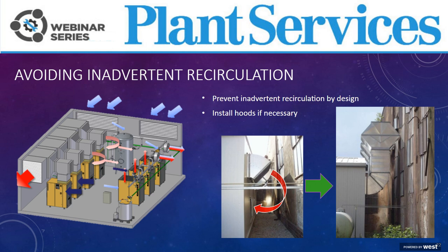Try to route exhaust air through the roof when possible, and take prevailing winds and other site conditions into account. It's typically not a problem to exhaust through one wall either, as long as the cooling air inlet isn't being pulled into the room on that same wall. If you have to do that, like we saw in the previous slide, then orient the exhaust so it's pointing away from the inlet. What we see on the far right is some hoods that are blowing the hot air up, which allows the cooling air at the bottom to avoid entraining that hot air.